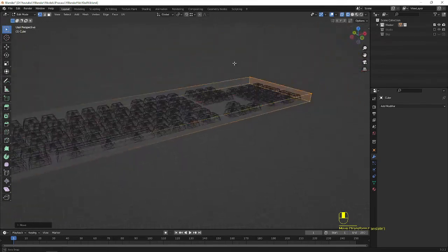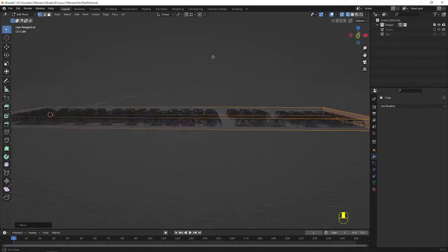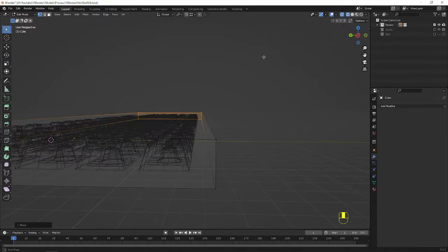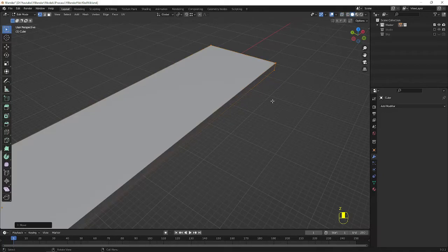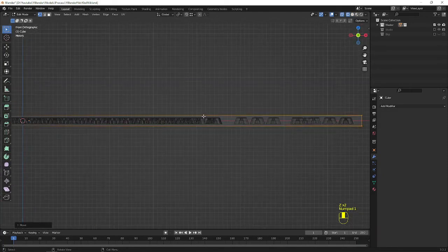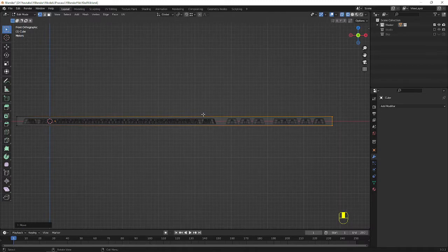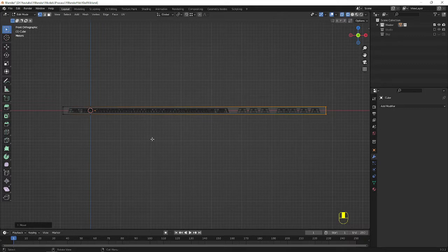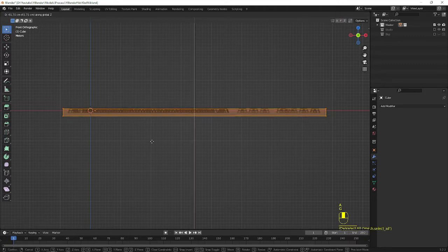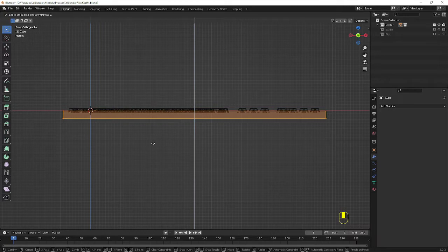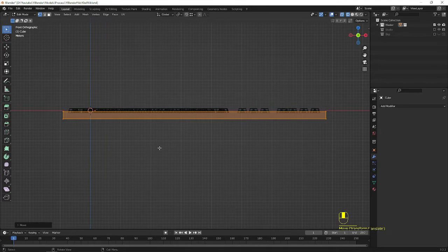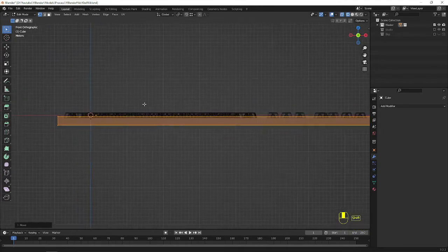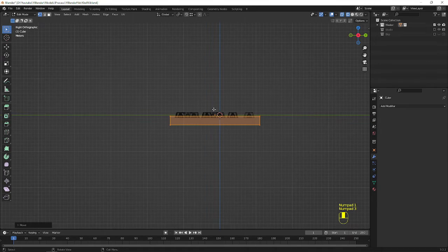And here we are going to make the difference. So how can we make the design and looks? So let's do further movement. So I go to the solid view, wireframe, and go to the front view, and I'm going to select everything and G Z to move down. So in this angle, fine. So after this go to the right view using the number 3.